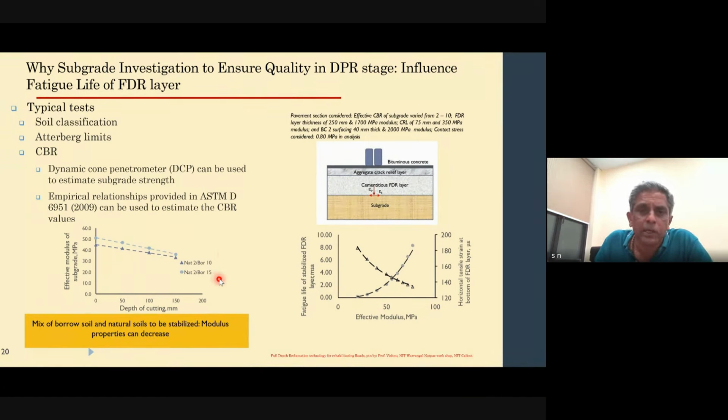Now, in terms of pre-construction, if I move a little bit further, there are a couple of things. There is going to be data that is going to be available before the start of your construction work. You're going to have multiple data sources at your site itself, which are the lab reports that have been prepared as a part of mix design, the soil survey reports that have been developed as a part of the initial DPR preparation, and then the mix designs that have been developed. Make sure that you're familiar with all these things even before the construction work starts.